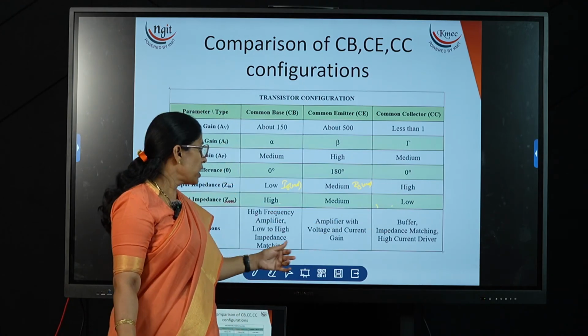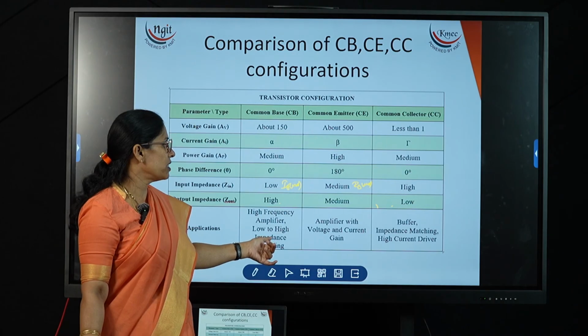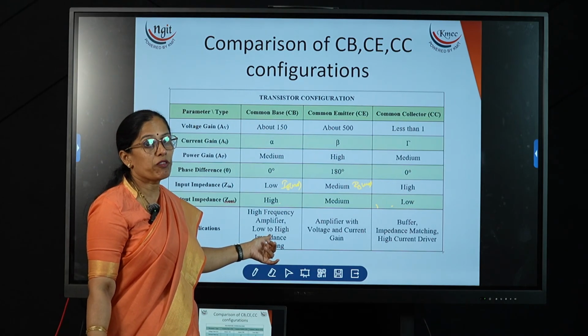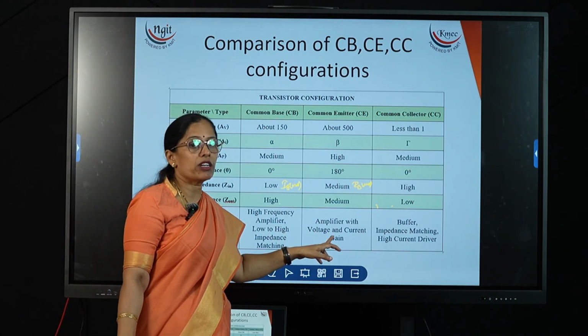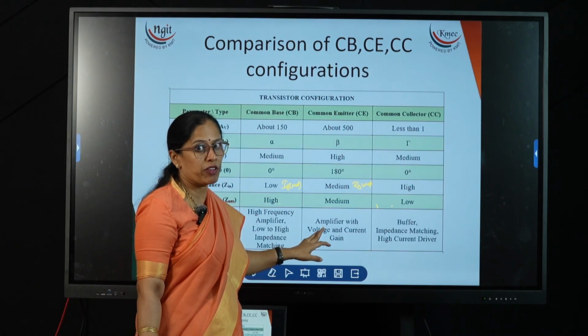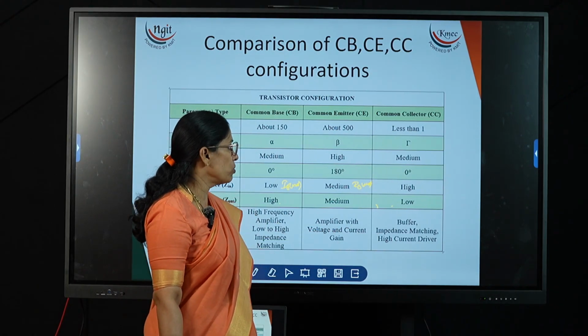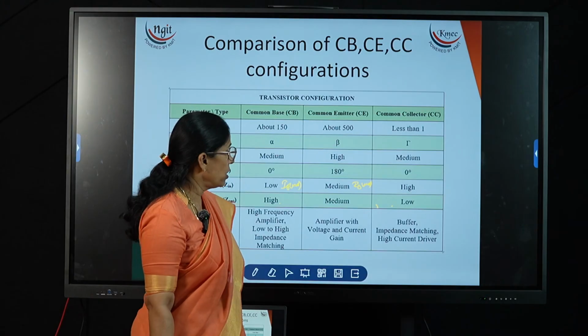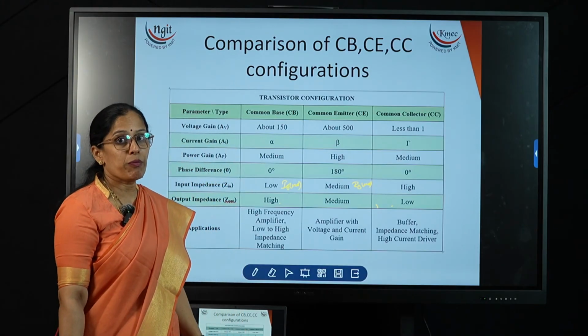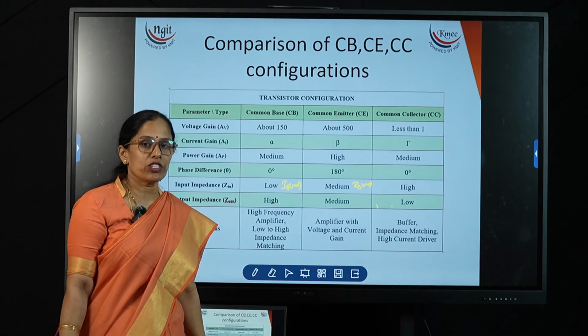Coming to applications, the common base we use for high frequency amplification, the common emitter we use for audio frequency amplification, and the common collector we use for impedance matching. So this is about the comparison of the three configurations. Thank you.